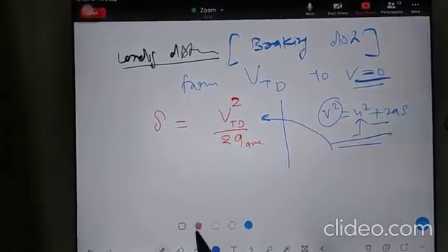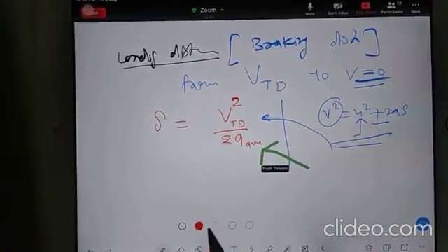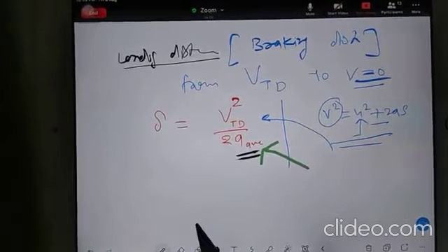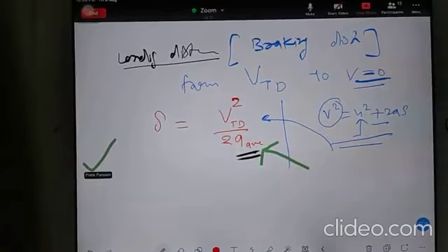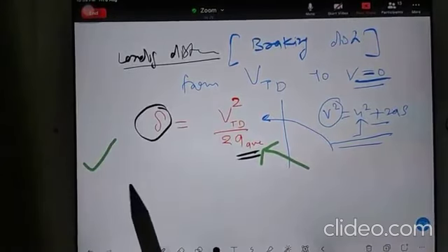That's all. And the same equation you can write in terms of the weight, average, because acceleration will also change, right? We use parachute, we use friction, we use braking, everything we use. So the retardation is also not constant. That's why we have chosen an average kind of acceleration. I hope you understand. Like you can see when fighters are landing on the carriers, right? We use all kinds of situations. Now the same formula, but in terms of weight of the aircraft and rho and everything.